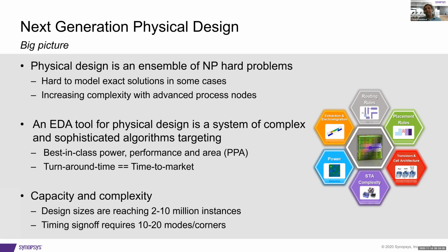Today, I would say a 3 to 5 million instance flat block, and I'm not talking hierarchical, I'm really talking flat, is very common. And if you look at sign-off complexities, most design companies are probably signing off at 15 to 20 to 30 corners. So when you put it all together and think about the amount of compute and complexity that a very typical EDA tool is dealing with, it's very, very high.